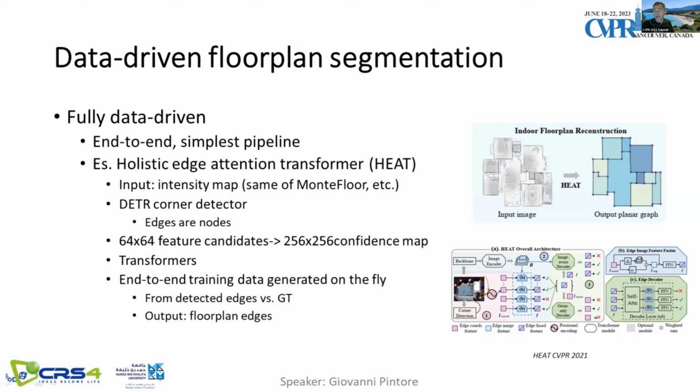We can apply a typical transformer approach. We have a fixed sequence and then we estimate from that a confidence map of the floor plan corners, refine it using such confidence map edges, and some candidates are extracted in order to model the walls.